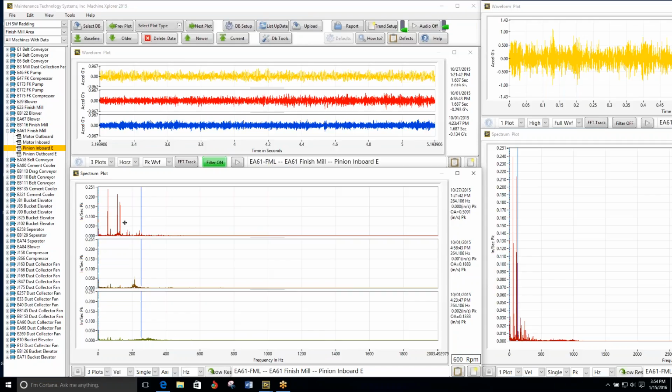Wow. Yes, this one is going to be gear mesh. Gear mesh on this guy is just under 60 hertz. We've got, well, they've got a ball mill out at the slag mill. It's got some gear mesh and bearing faults going on at 0.7. Wow, yeah.